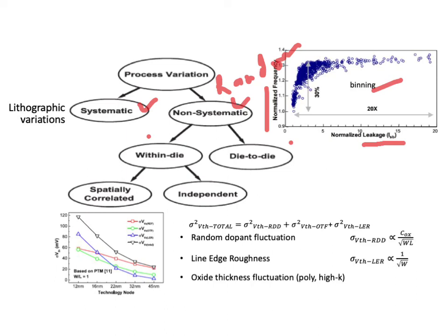This is for the same design, meaning all of these dies are designed to operate at the same speed, and your front-end design gives you a magic number from the max delay, the maximum operating speed. But after fabrication, process variations lead to a 30% variation in the achieved operating speed.